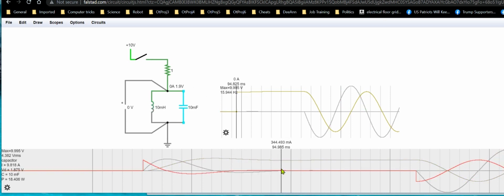But at any rate, after all this stuff settles down, you end up with a situation where you have 0 volts, because the capacitor is completely discharged. All the capacitor's energy, what little energy that capacitor got into it at first, was dumped into the inductor, which the inductor then eventually dumped out of the system, basically. So it ends up stabilizing at like 10 amps, and there's no further oscillations or anything like you see here. But eventually, you know, when we get to this point, I actually open the switch.